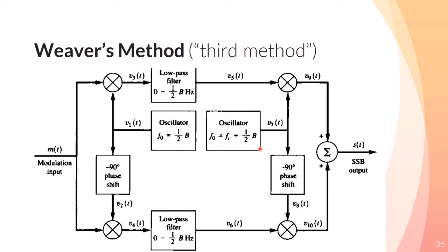This complex signal or pair of real signals is then low-pass filtered to remove the undesired sideband that is not centered at zero. Then, the single sideband complex signal centered at zero is up-converted to a real signal by another pair of quadrature mixers to the desired center frequency.